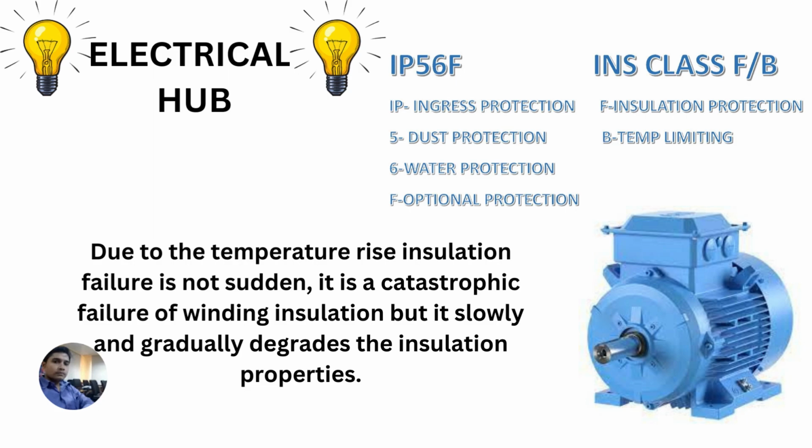But the temperature rise doesn't mean that the insulation will fail as soon as the temperature rises. It depends upon the time of operation, and it is also a cumulative process, meaning it will degrade the lifetime of the motor.